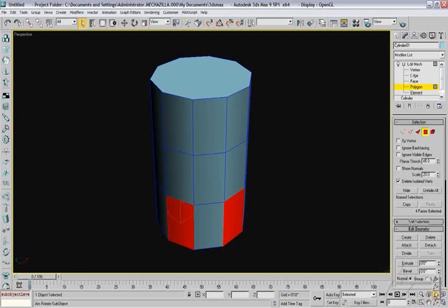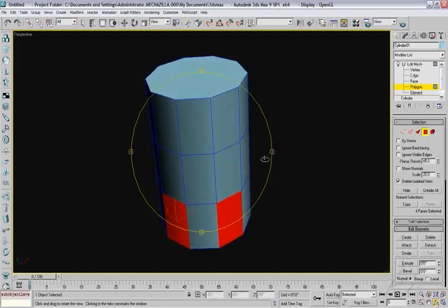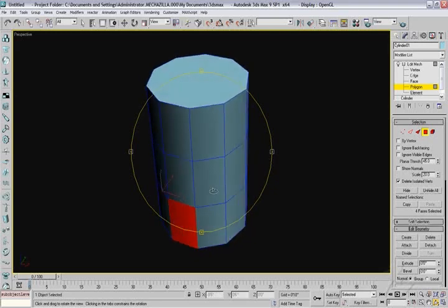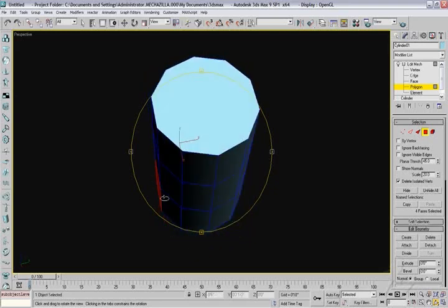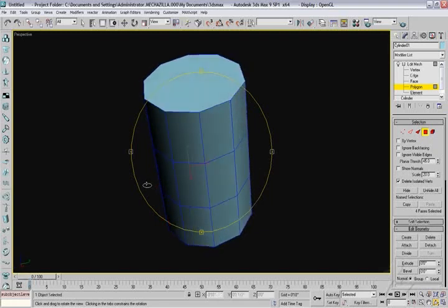The Arc Rotate Selected is the white one. If you hold down your left mouse button over it, it will roll out and you get 3 choices. The Arc Rotate Selected will use your object that you are working on as the pivot point for your arc rotate pivot. And you can go ahead and rotate around your model and try and get to another view here.